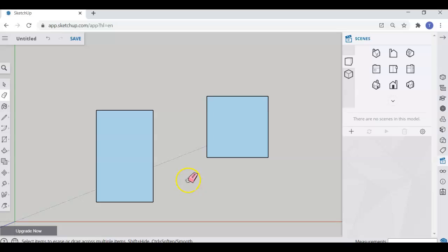All right, last thing I want to show you for this first day is to actually build a component, in this case, a stud. If I wanted to build a stud here, I could put the dimensions in a rectangle. If I'm looking from the top down, it's going to be a rectangle, 3.5 inches by 1.5 inches by 3.5 inches.